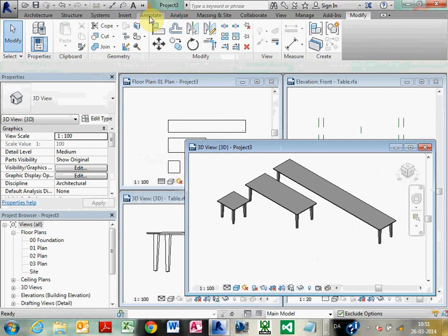little thing in the family and then reload into project all the time, because if you make more complex families, if it gets too complex or you make an error, Revit will give up and say can't make object a delete type. It wouldn't tell you where you have made this mistake. So if you all the time make a little bit, try it into the project, you have always only one step back to find the error. So and sometimes it doesn't behave in the same way in the project as it does in the family. So keep testing in the projects.